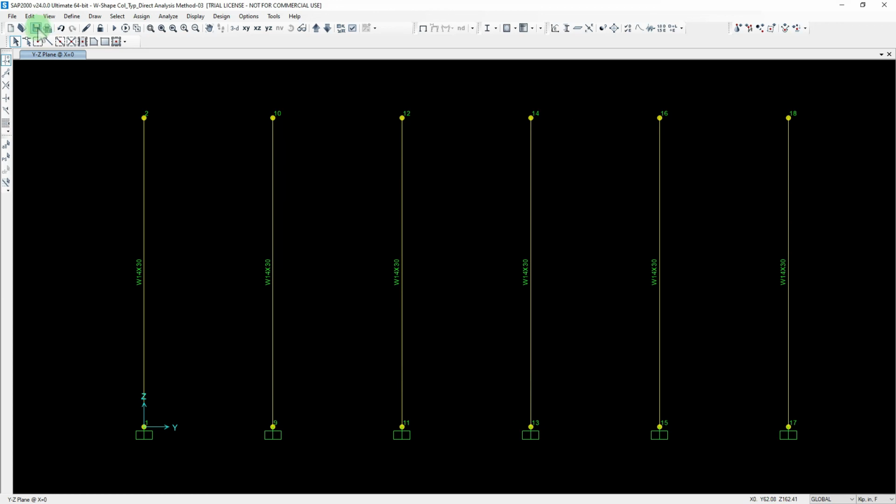I like to use kind of square columns whenever I design a column. So our typical column section that you would want to start off with, it's a little insider structural engineering knowledge, would be the one that is boxed, is more square, i.e. the flange width is kind of equal to the depth of the column.